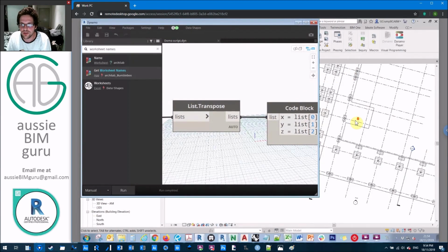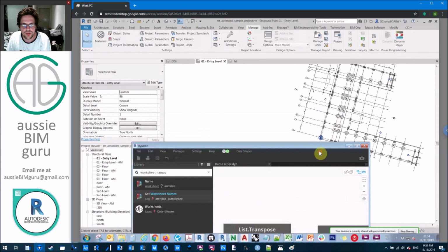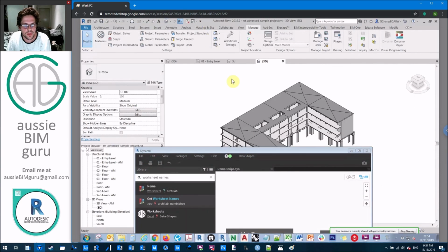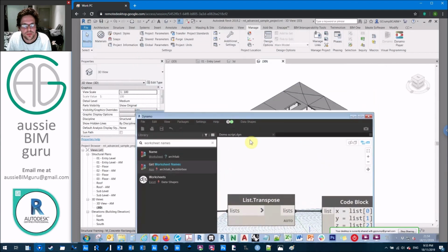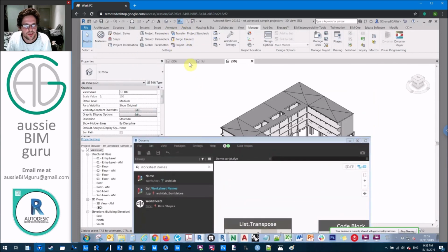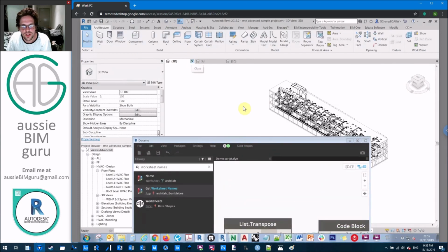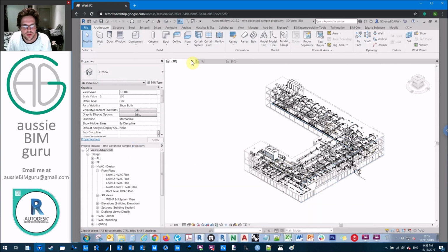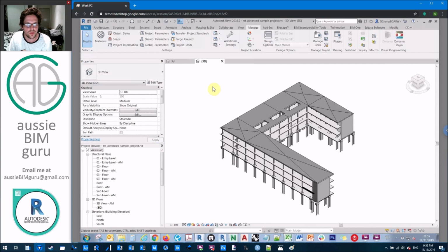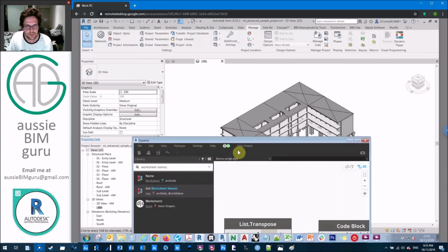So if I just go back to my Revit model and I'll just jump into 3D, make sure I'm actually working upon the right Revit model, which I am. I might just close the mechanical model, which I have open on the side. This is the mechanical model that I've taken all those ducts into Navisworks from, but we're going to work within the structural model so that we can see the location of all the mechanical clashes on the beams. Alright, so we'll just reopen that.